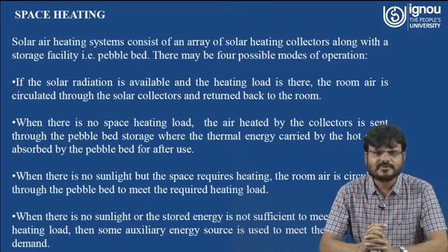First, if the solar radiation is available and the heating load is there, the room air is circulated through the solar collector and returned back to the room. When there is no space heating load, the air heated by the collector is sent through the pebble bed storage, where the thermal energy carried by the hot air is absorbed by the pebble bed for later use.